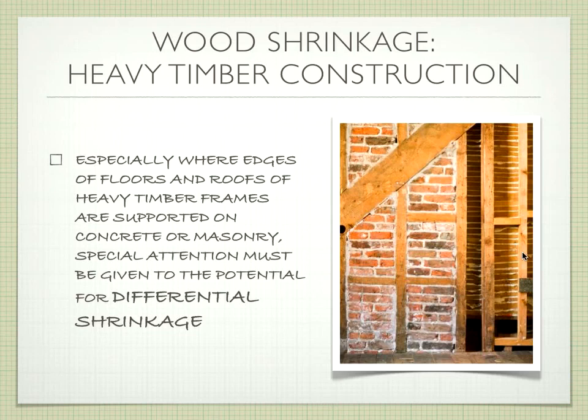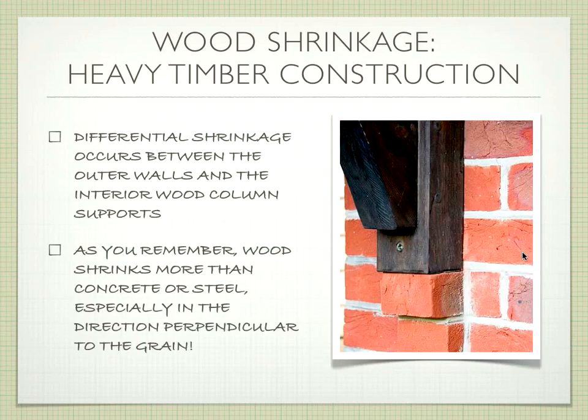So you run into a problem if you have a masonry frame that's in juxtaposition with a heavy timber frame, because the wood's going to move around and the masonry isn't. So we have to think about how we make these connections such that we don't have the building fall apart on us with that movement. Okay? So that movement is called differential shrinkage.